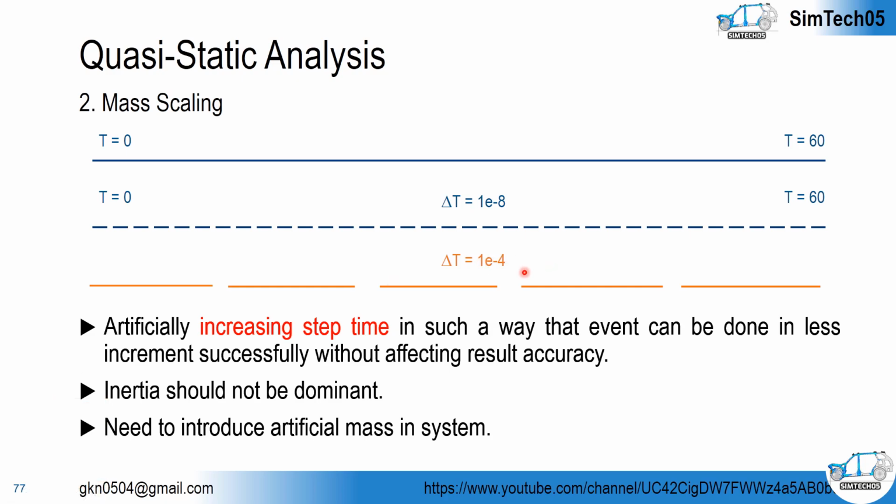we have to make sure inertia is not dominant. If inertia dominates, then it will not remain a quasi-static analysis, it will become a dynamic analysis, and that dynamic condition will also be artificial because we artificially increased the mass.